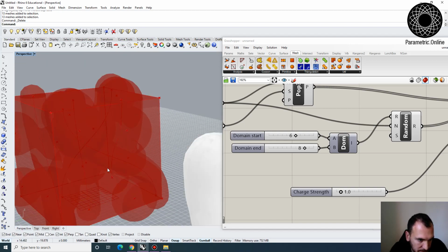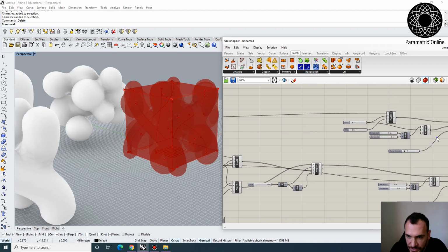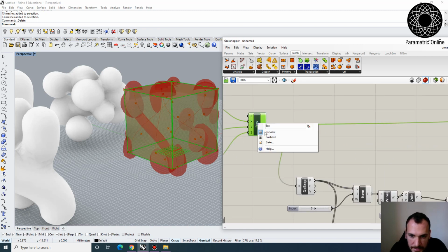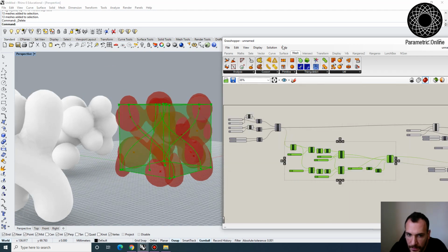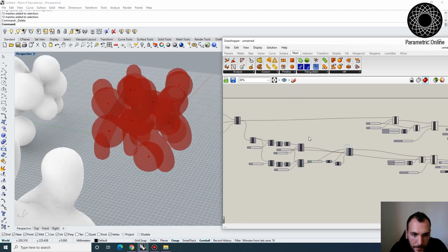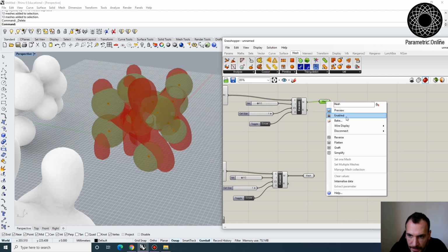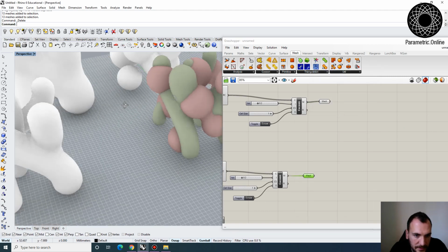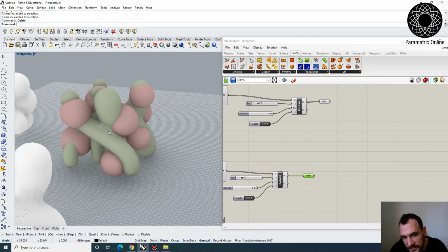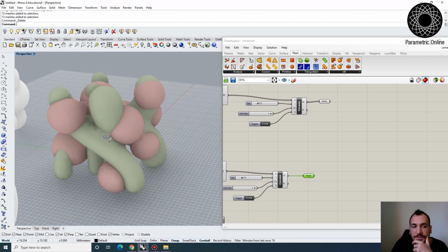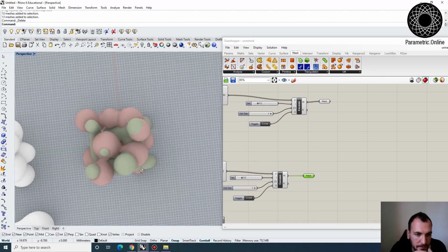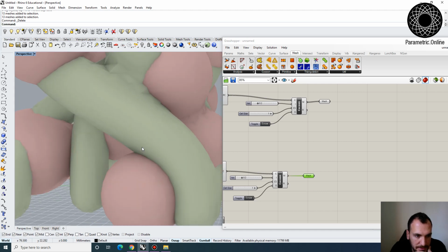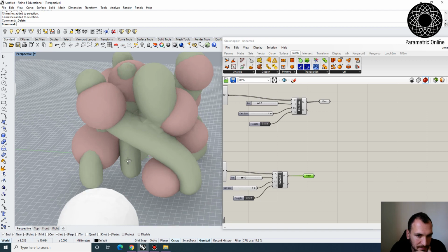one thing though, because the curves and the points, they're actually going to create 2 different sets of geometry. So if we can hide the box, let's see, hide these guys as well. If I bake this, you're going to recognize that they're actually discontinuous. If you want to make something more continuous, you can see they're actually causing 2 different sets of calculation. So we can go with one or the other. You can also combine these, but if you combine these, you're going to get these sorts of breaks or kinks in the mesh. So maybe that's not something we want.